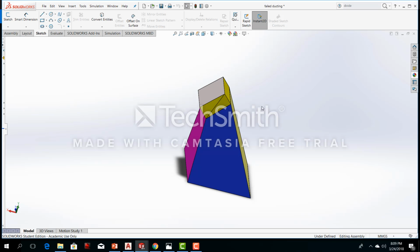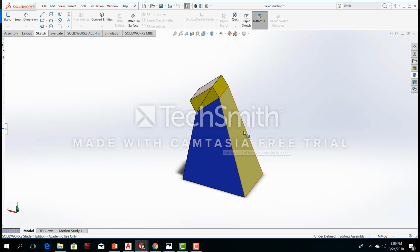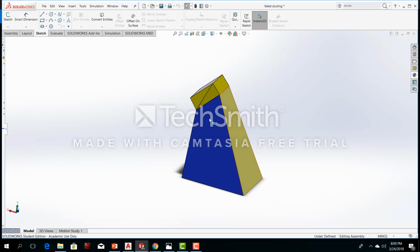So the rationale I give for this solution would be that we know that the bottom transition piece is going to work based on principles, and we know we can develop it out, because we can use rebatment and we can use triangulation to find true lengths, and so we can see all the true lengths that we need to find in that, and we know that's going to work.